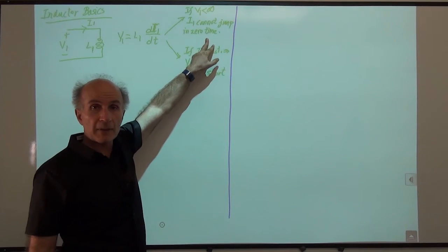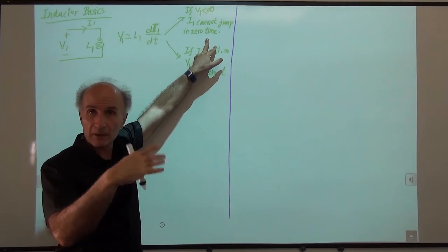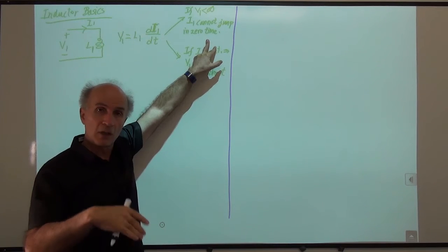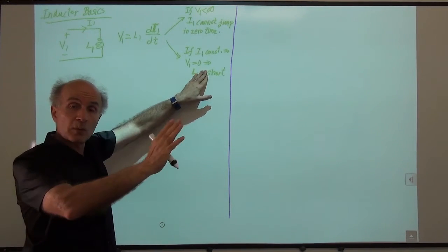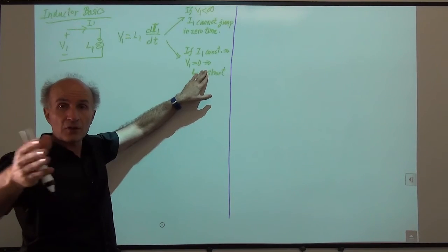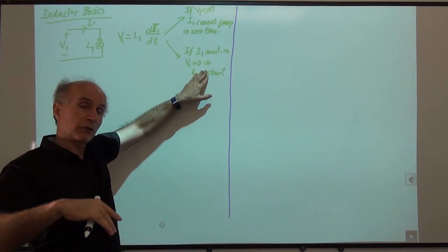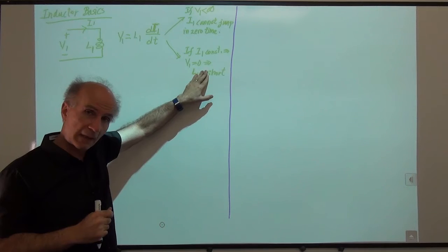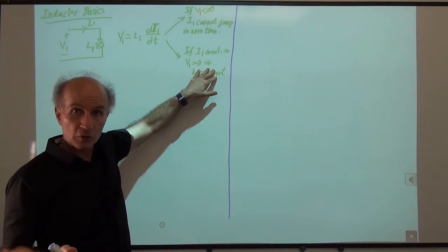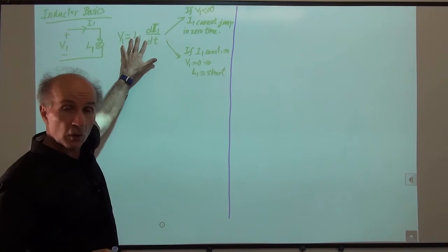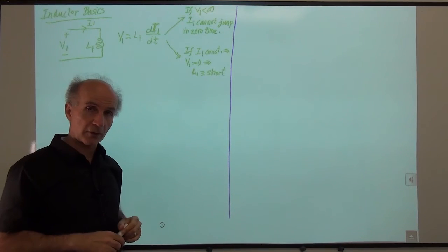This typically happens when there's a switching event, something switching in, something switching out, or when there's a step somewhere. And this typically happens near the end when things have settled, no current is changing with time, so the voltage across the inductor is 0. But we always have to remember these. Again, if you don't remember them, you go back to the original equation for the inductor.